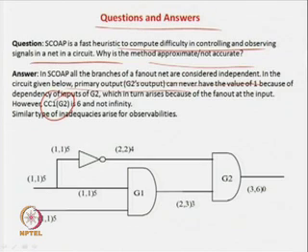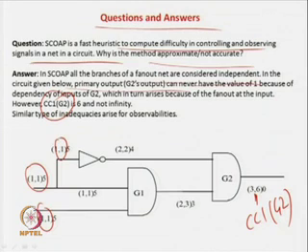So, CC1 of G2, that is how difficult it is to make this line 1. Let us see. The primary inputs are 1, 1, and the fan out will be 1, 1 over here. This is a level shift, so it is 2, 2, because for an inverter you just add 1.